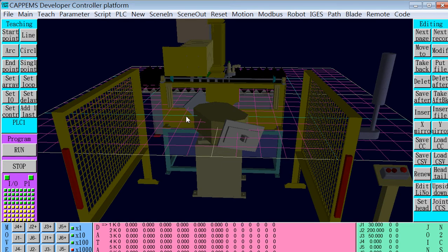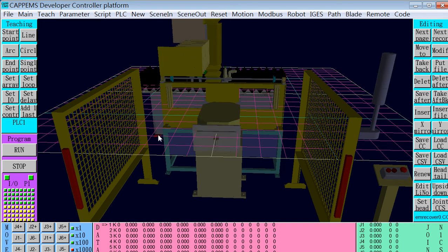And most important is the I/O control, the window. Before turning, we have to lower the window by using Y6 on. The window will go down. You see here immediately. And Y6 off, the window will be up.